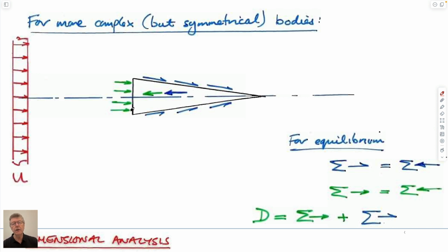A visual, I guess, of what's going on is that you expect there to be two components that are given in this expression. So if you want to calculate the forces, you have it from an integral of P dA plus an integral of tau dA plus some other terms, right? So these represent the two origins of these forces. One is due to pressure, the force on the side of the truck on the San Francisco airport apron, which is just by killing this velocity at this stagnation point and then pushing. And then the effects of the drag, the shear drag on the side.